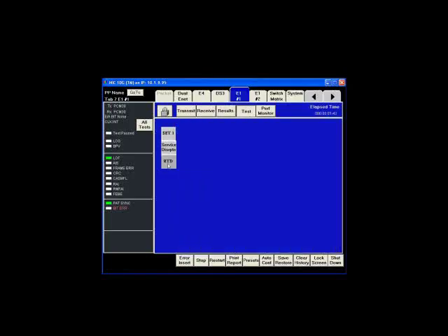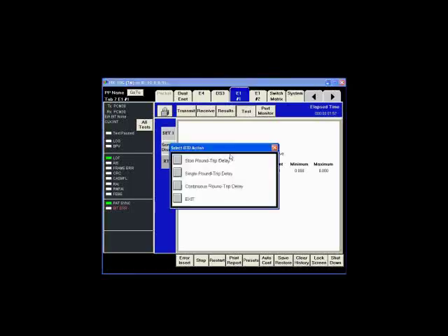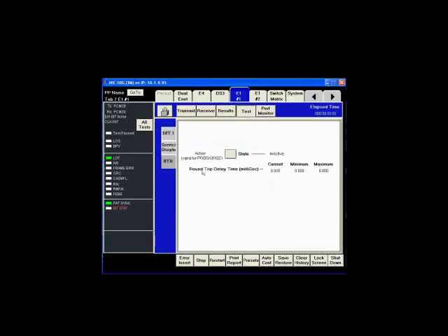Okay, and then RTD is round trip delay. Like when you send a signal with the test set, how long does it take for that signal to go out to a loop and come back? And it's done just, I can do a single and continuous, kind of the way as before. Like it just does one quick test now. Or continuous, it'll just continually look for how long does it take. When it sends this pattern, how long does it take to receive that same pattern back?